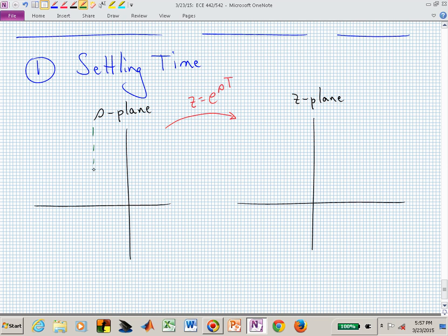Let's say that we now have poles maybe all stacked up along a line with the same real part. Now we could have poles living on this. Well, that's not a very nice vertical line, but it looked okay on my tablet until I came and looked at it in the class. It's okay. So now if you had a bunch of poles on that vertical line, where would those map into in the z-plane? Those are now going to map into a circle, aren't they?